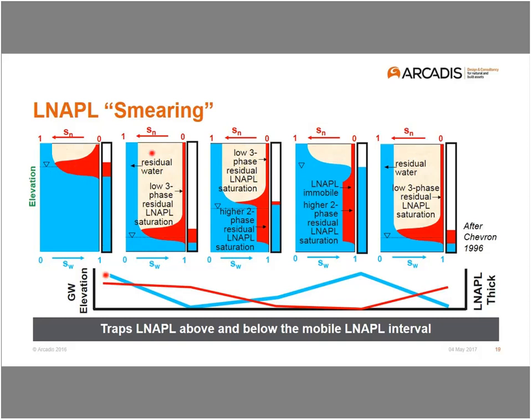When the water table drops, so here we have the water table going from a high point down to a low point here, the NAPL drops with the water table. Remember again, there's NAPL above and below the water table. But it also leaves behind a residual saturation in the vadose zone. And this is the 3-phase residual saturation. So there's still some NAPL in the well, as this portion of the NAPL is still mobile enough that it can drain into a well.